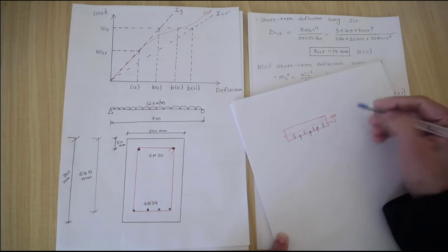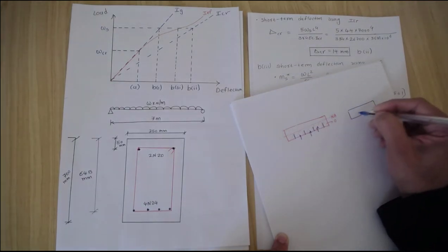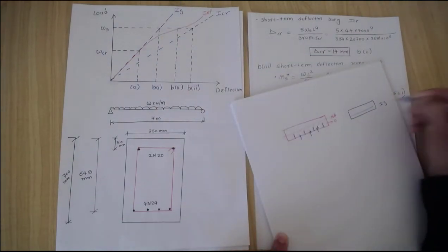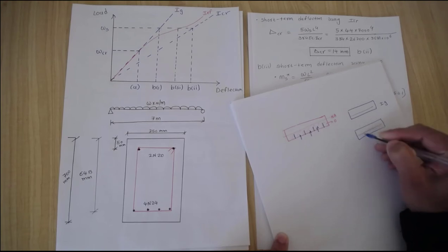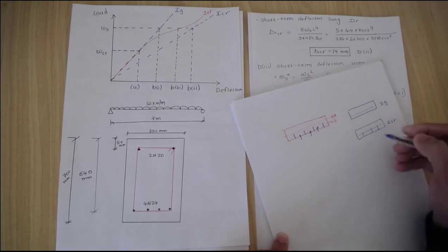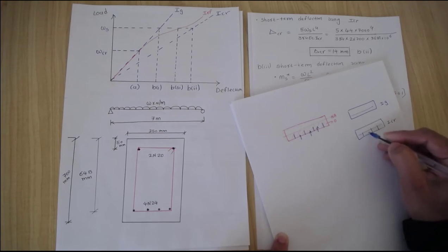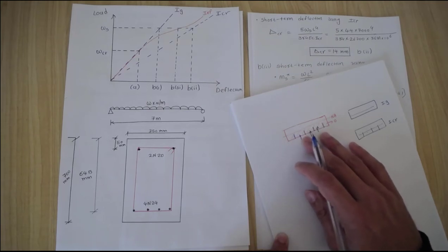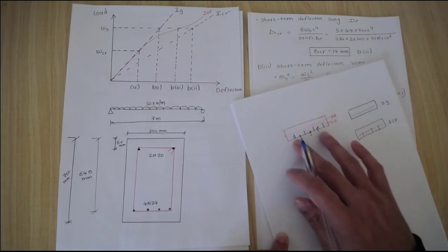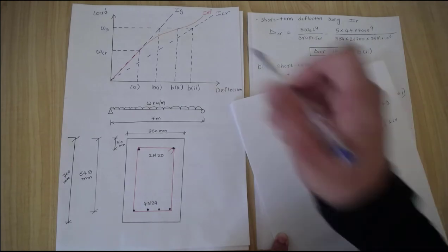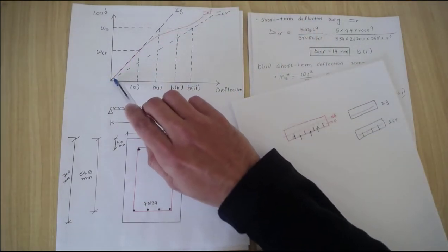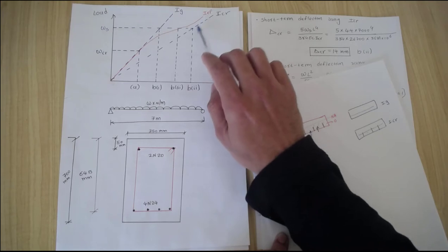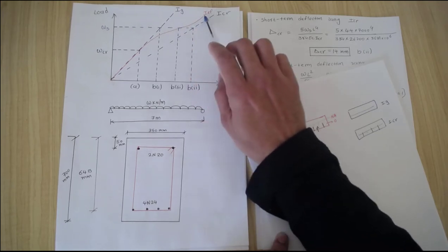I gross is when you have a cross section which is not cracked, fully, let's say this is the reinforcement and there is no cracking, then you have Ig. I crack means that if you have a crack present, then you have Icr, but this Icr does not take into account the concrete contribution in tension. Of course, the concrete will contribute partially in tension. So not here, but between the cracks it will carry some of this and increase the bending stiffness. When we do the test, it shows that it has some larger stiffness than the one that uses I crack. So we need to find this I effective.